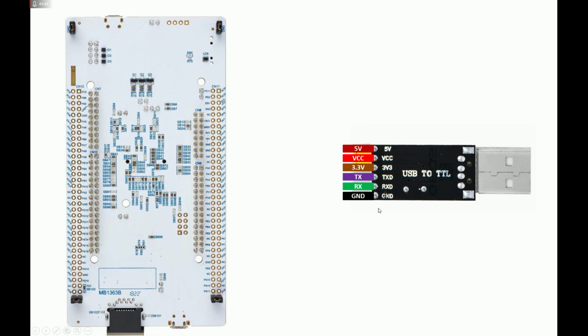For our application like this, where we are using this as a serial monitor, we will be sending strings or text, whatever, we just want a serial monitor just like an Arduino. But here, unlike Arduino, we will be using this device to send the data to our serial terminal over the computer. So for that, only 3 pins are required, TX, RX and ground. We do not need to power up this device through the microcontroller, because once you insert the USB into the computer it will automatically power up this device. And you may use this power to power up your microcontroller if you don't want to power it up from the USB port. That's up to you.